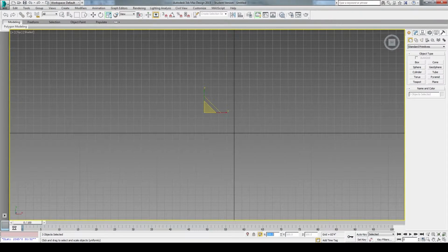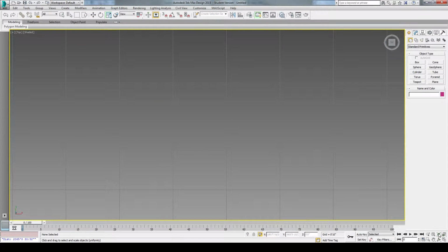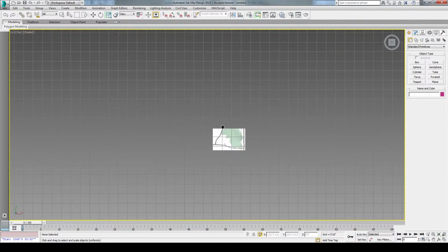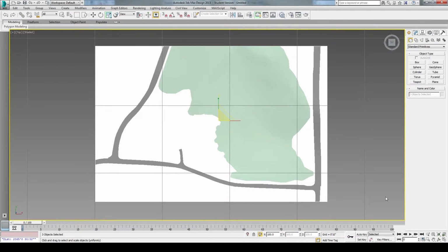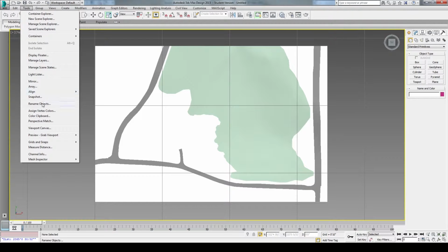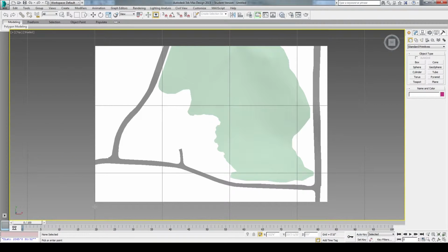Now, as soon as I hit enter, the model seems to almost completely vanish, and that's simply because it's dropped from 1:1 now to 1 inch equals 60 feet. So use Zoom Extents All to zoom the model back in. And now we're going to remeasure to see if it's matching what we had in Revit on our CNC layout sheet. And it does. We're right at the correct dimension that we were seeing inside of Revit.